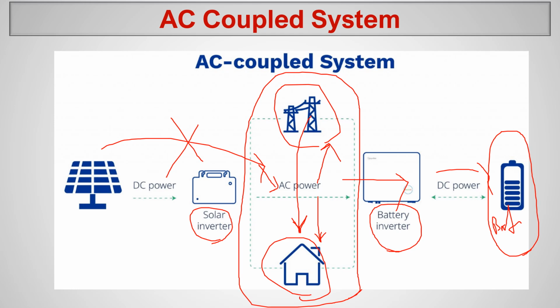So if you have an on-grid system, you don't have a problem with the grid. I mean, problem means power cuts, frequent power cuts. You don't need a battery. Simply, you don't want a battery. But people with a lot of money say it's better to install a battery. I want to store excess power from the solar PV. For those options, AC coupling is more suitable because we have a grid. The grid will play the major role here in this area.